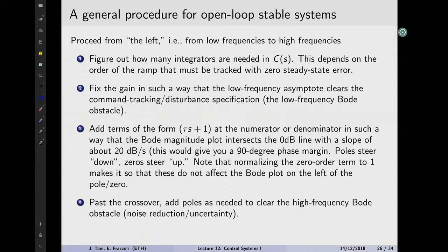And remember that all of this makes sense only with proper transfer functions. So you need to have, at worst, the same degree at the numerator and the denominator of your combined controller and plant. You'll see that you will add the same number of poles and zeros. And one way of seeing that is the lead and lag networks that we just studied.